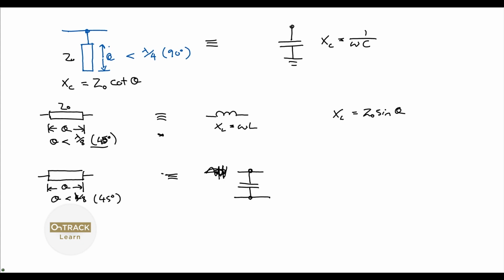Okay, because every transmission line, every trace on the circuit board, you could break it down piece by piece, has capacitance to the ground plane. So it's always there. So if you want to say, well, for this little portion of trace on my PCB, what's the equivalent capacitive reactance of that section? And you can work that out using this transform as well.